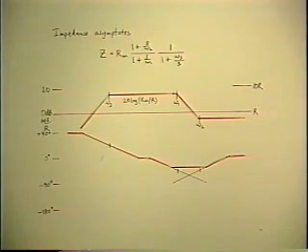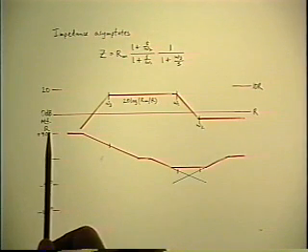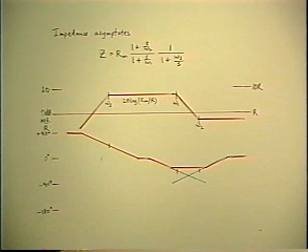Unfortunately, a lot of people don't bother doing that. They just write a 0 dB scale for impedance. And if you don't say what it is, the implication is the reference resistance is 1 ohm. Maybe it's 1K. But you don't know unless whoever drew it specifies what units you're using. So to be strict about it, you should always specify what the reference value of resistance actually is.